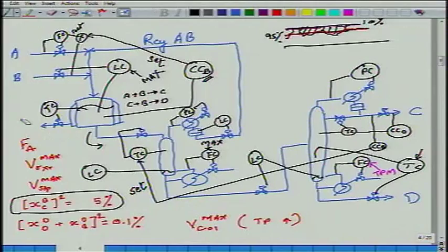Okay. Now the point is, when I'm increasing the throughput manipulator set point, which is the boil up in the second column, this temperature is bound to increase. Temperature in the reactor is bound to increase by the action of the stripper level controller. Then temperature reaches maximum. What do I do? So then I say, well, temperature has reached max. This has now reached max, maybe slight back off. When I say max, if any back off is necessary, that back off is implied. Okay. Now what do we do?